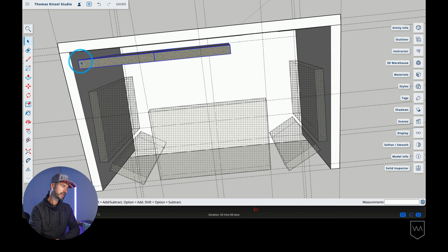And you can see the edge of the modules are snug against the sidewall, and that is going to increase the bass absorption, because bass will accumulate there at any of the room seams. I much prefer using these types of modules, especially where low frequency control is such a big issue, than the little wall-mounted modules. Anytime you see somebody mounting a 2-foot by 4-foot little module on the wall, it's the worst possible acoustical waste of time, because you need the module off the wall a little bit to be acoustically effective, because it works based on velocity, not on pressure.